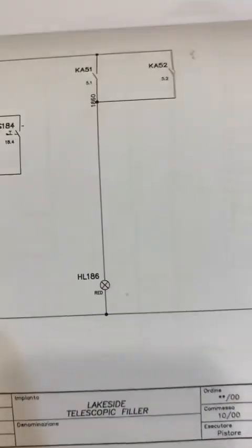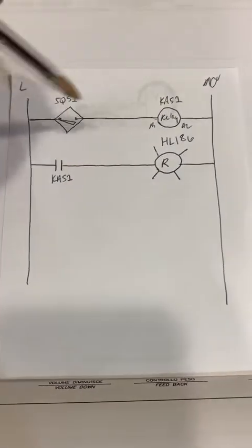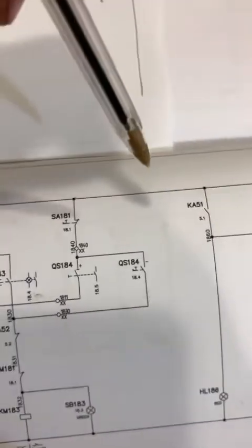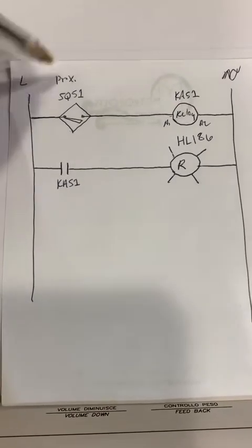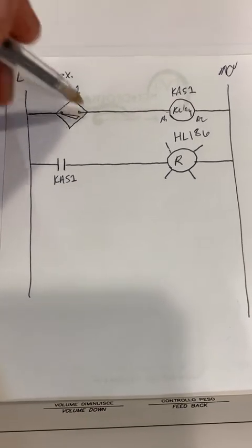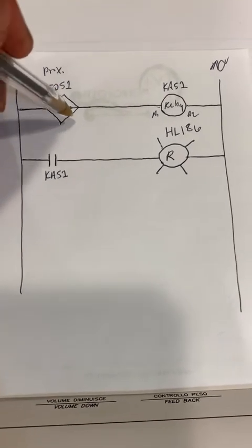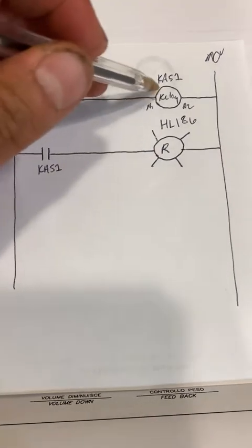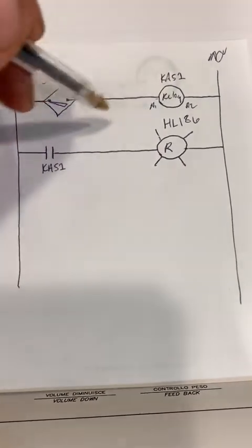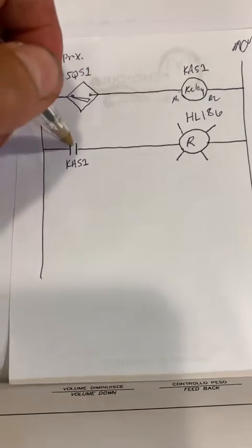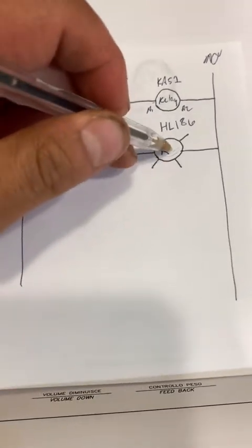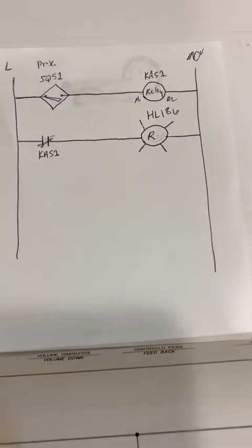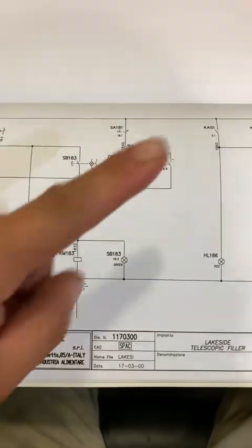That's all you do. And if we were to put that circuit that we just went over on the IEC standard drawing to the NEMA standard drawing here, this is how it would look like. You got power coming into the prox sensor. The prox switches when it detects metal. It's going to energize the relay. The relay then switches state, which will then close this set of contact and allow power to get to our red light. Our red light illuminates. It's that simple.